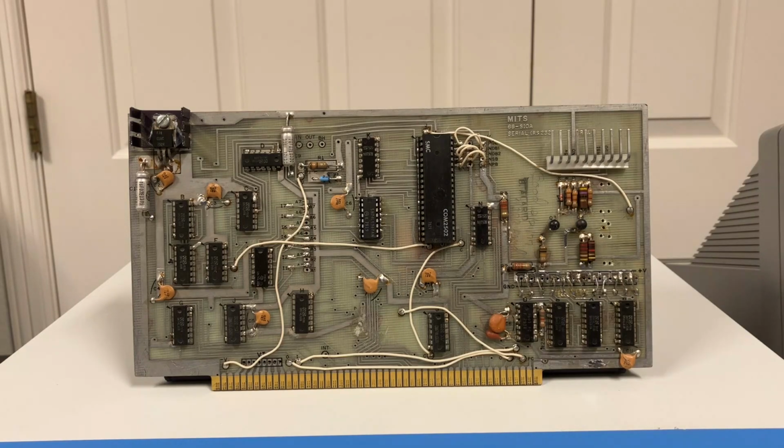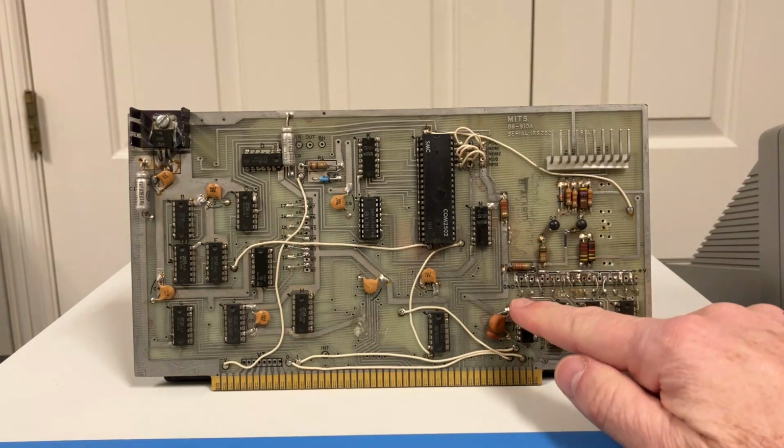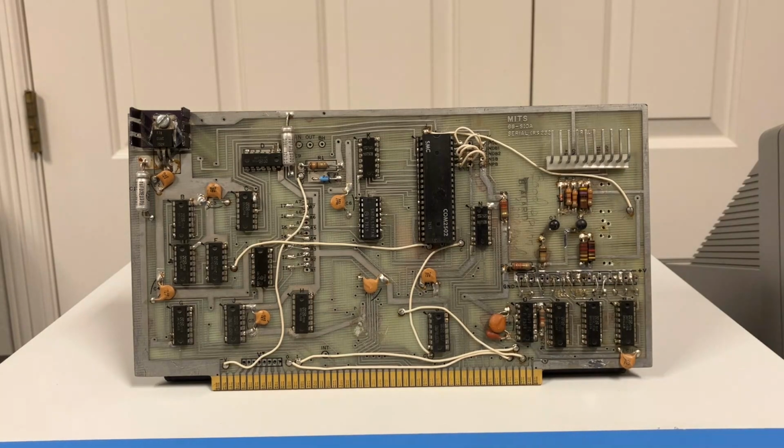And finally, we need to set the baud rate to 300 baud. And that's done with all these jumpers down here. There's a bunch: 1, 2, 3, 4, 5, 6, 7, 8, 9, 10, 11, 12. It takes 12 jumpers to set the baud rate, and they're all solder jumpers. So not an extremely convenient board for changing the baud rate. But once you have this set up to run at 300, you'll probably never change it again if you're making this part of your cassette interface.